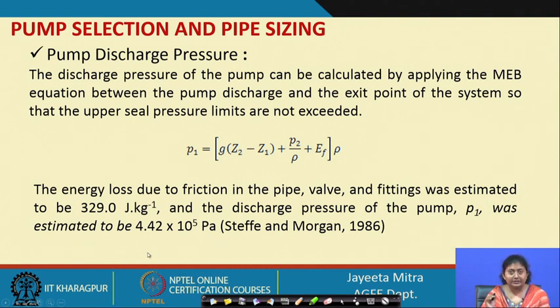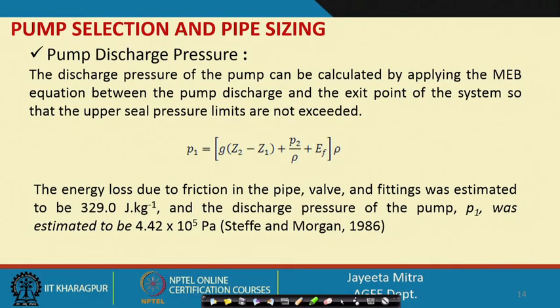So, this is how the understanding of fluid behavior will help you to eventually design the whole system, starting from the velocity distribution, then residence time in a processing channel, volumetric flow rate, then pressure drop, then the whole energy balance, pump requirement, volumetric flow rate requirement of the pump, and finally the discharge pressure.